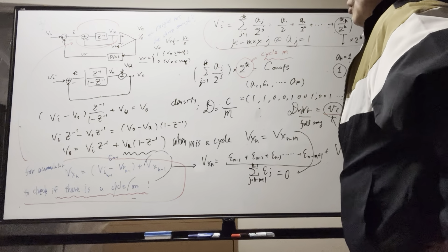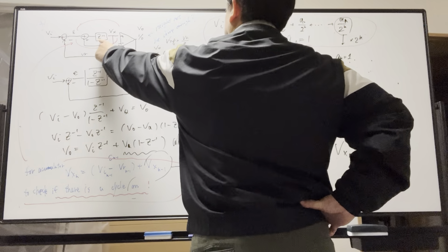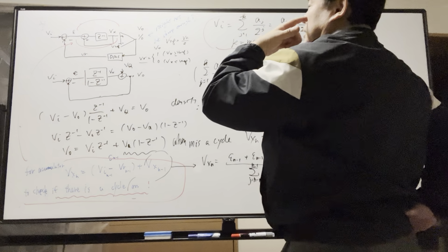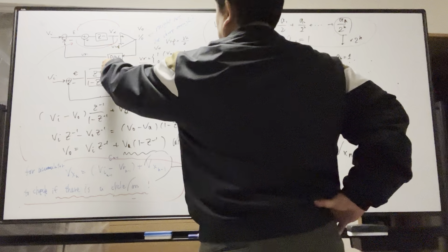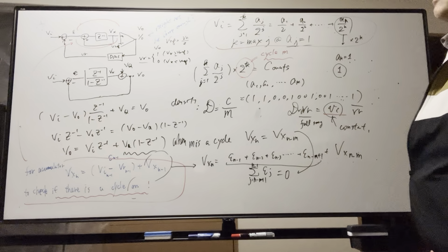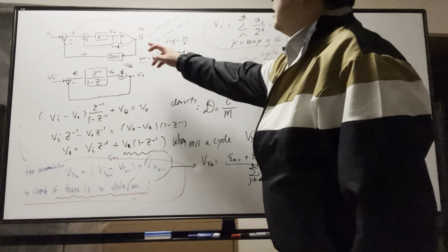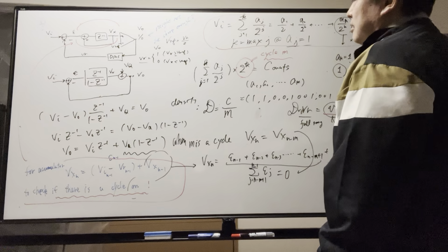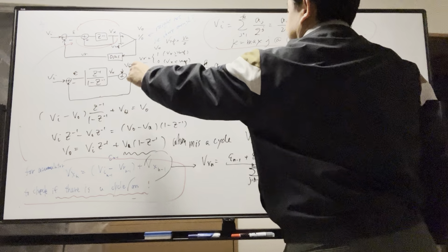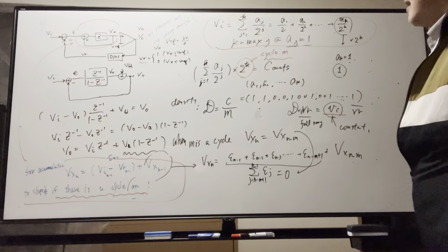Sometimes you need to change this delayed accumulator or integrator into a non-delayed integrator and apply a one-step delay to the feedback, to avoid metastability. But in many cases I see there's no metastability for a fast latching clocked comparator.